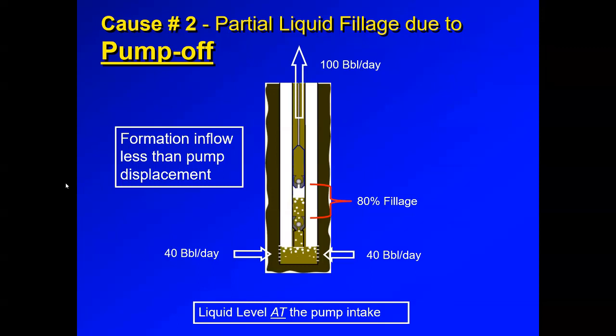Maybe you just don't have enough inflow to be able to match that inflow with your pumping capacity. Then you have to opt for options like stopping the well for some time, turning on a pump off controller, or a timer, or something that allows you to decrease the pumping rhythm.